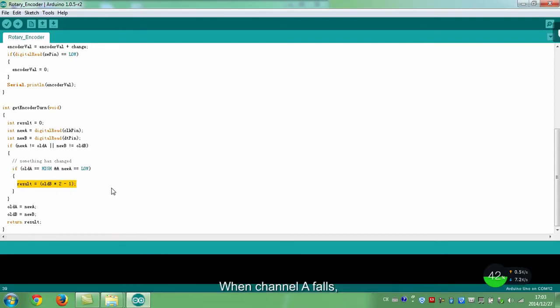When channel A falls and channel B is high, it means the rotary encoder rotates clockwise. Result is 1. Otherwise, counterclockwise. Result is -1. That's all for the code.